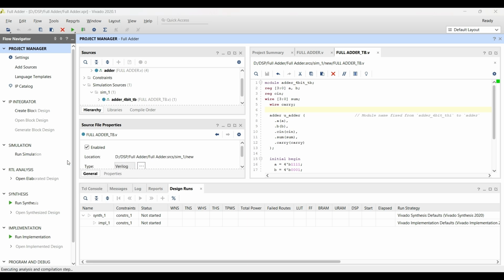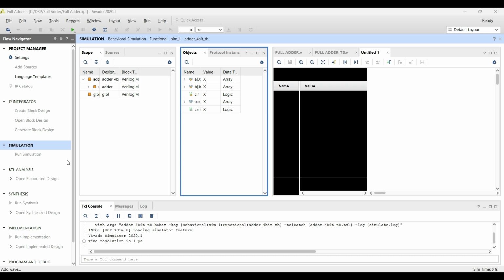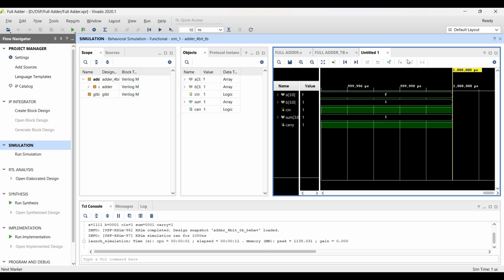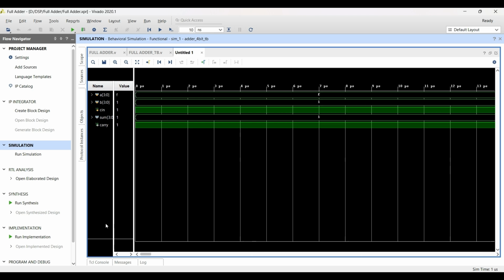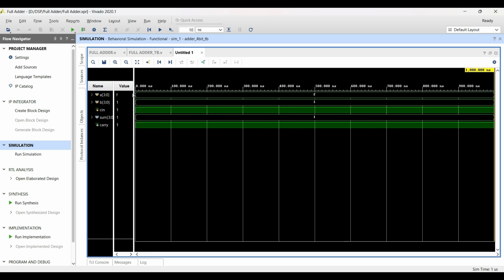Now the simulation is getting executed, and we will get the output window. See here, the window is opened. So just full-screen this window. This is in the range of picoseconds. If you want to make it in the range of nanoseconds in order to see the waveform correctly, click on zoom fit. So now the complete plot would be in nanoseconds.